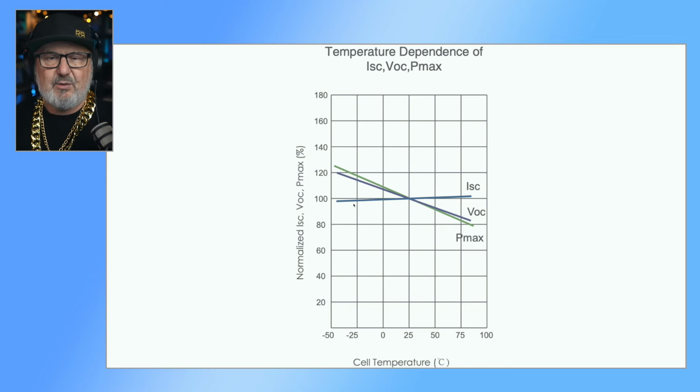And why do I not consider the fact the sun warms up the panels? It's because it's the highest possible voltage under any operating condition. And that actually can be a freak moment. For instance, it's a winter's day and it's cold and foggy and the sun has risen, but it doesn't penetrate through the dark clouds. So the panels are really at their minimum temperature. And then the fog clears and the beam of pure sunlight hits those east-facing panels and the voltage just goes whoop, straight up momentarily until the panel warms up. But that instantaneous voltage is a hazard.